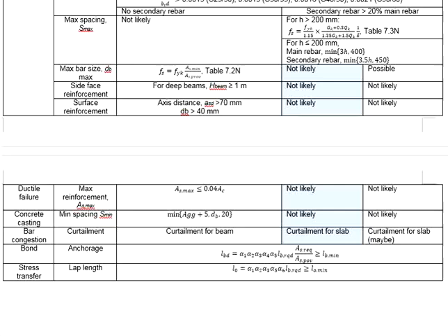Let us proceed with other serviceability requirements for the design of reinforced concrete beam, slab, and staircase. We talk about the maximum reinforcement bar areas. The maximum reinforcement bar area is set in order to ensure that the RC member is always under-reinforced. When an RC member is under-reinforced, that means when it comes to failure at the ultimate state, the tension reinforcement bar should fail first.